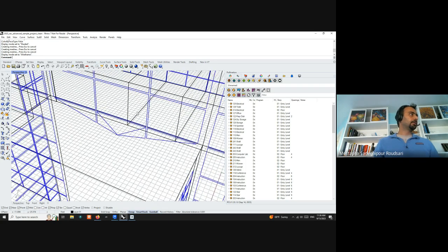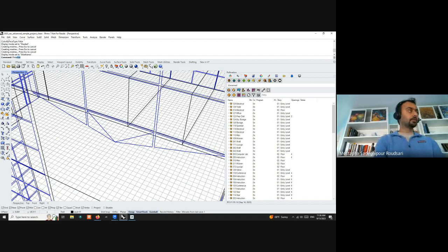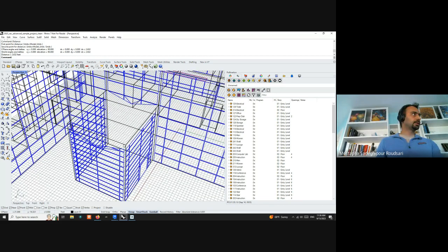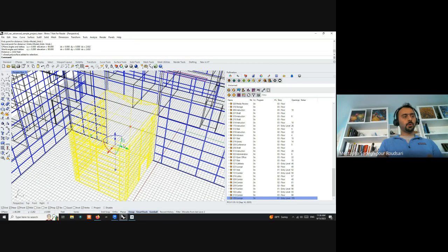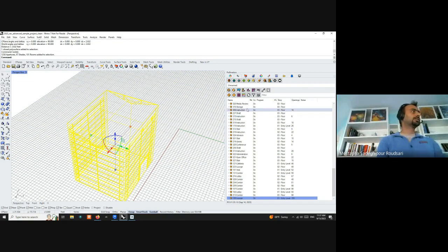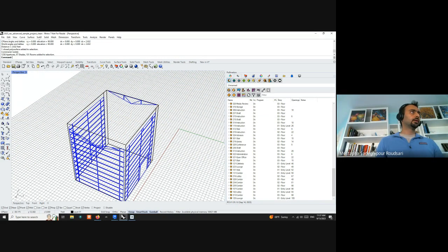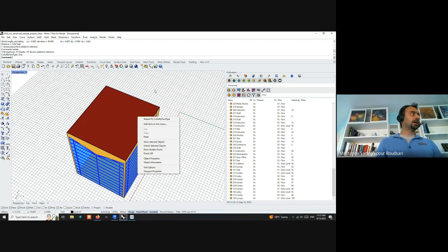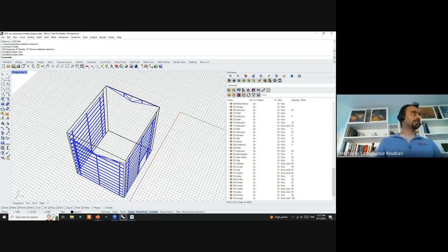So now let me go here and do the distance, from here, perpendicular. So this should be 2.63. So I'm going to bring this 2.6. And to make it easy, there are two ways. I can either go edit in place, or again, I like isolate much more because it gives you only one, right? So now you can see this room here. So now I can go and just try to edit this.